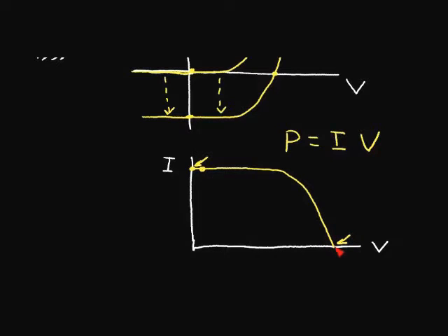Now let's look at this point over here. At this point, we have no current flowing in the solar cell. So the circuit is open, and we're looking at a high voltage. But since our current is 0, we extract no power, so that's not very useful. But if we can operate over at this point, then the power that we can extract from this cell is the area under this part of the curve. Is this amount of current times this amount of voltage here.